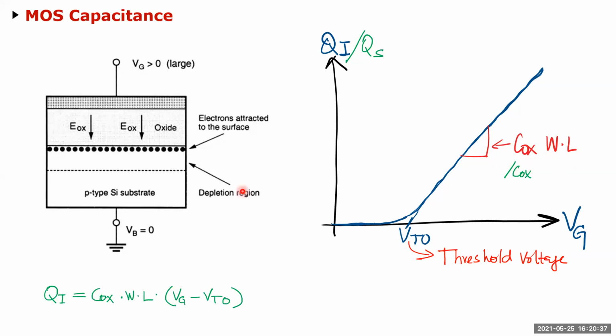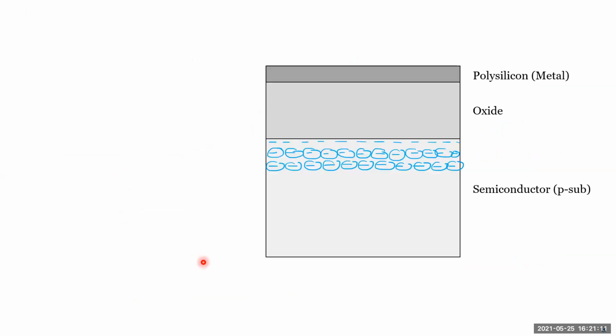If you want to calculate the charge, then obviously it depends on the excess gate voltage. We call this excess bias, excess voltage, Von, a lot of names for this voltage. Whatever the excess bias above the VT is, times Cox times W over L, that's the charge which is going to form here. So this is kind of a nonlinear capacitor in the sense that it doesn't turn on till VT, but once it turns on, it is a linear cap. So it's kind of linear and nonlinear at the same time.